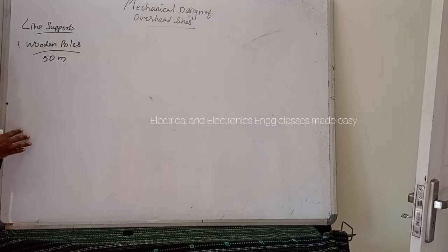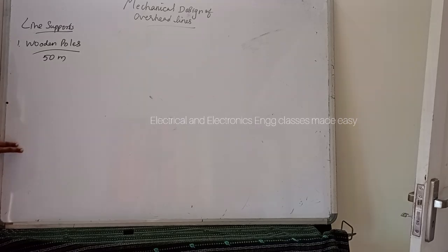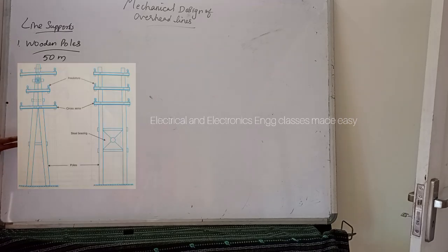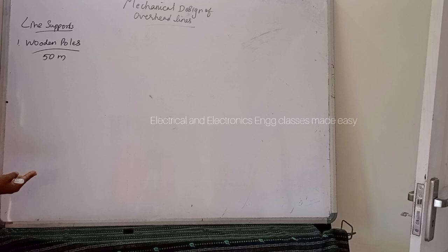And the wooden poles generally tend to rot below the ground level, causing foundation failure. In order to prevent this, the portion of the pole below the ground level is impregnated with preservative compounds like creosote oil. Then double pole structures of A or H type are often used to obtain higher transverse strength that could not be economically provided by means of single poles.